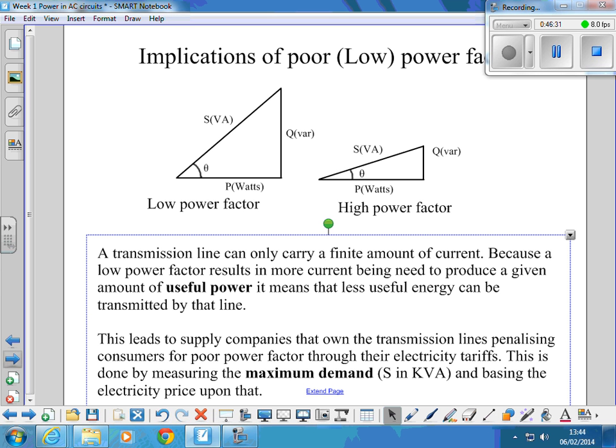And they do that through the tariff. What they do is they make a monthly charge dependent upon your maximum demand in kilovolt amps. If I remember back, I used to check this when I worked at Fibronal, and they'd record what the maximum demand was each week, and they'd keep an eye on it. That was a meter that had a needle on it in them days.